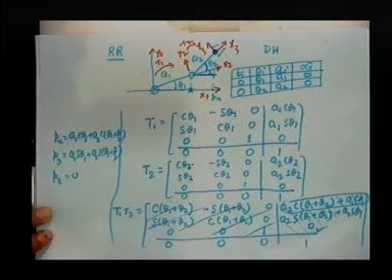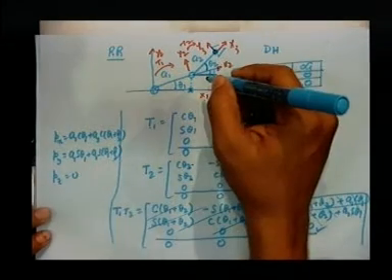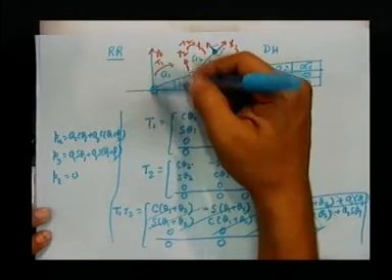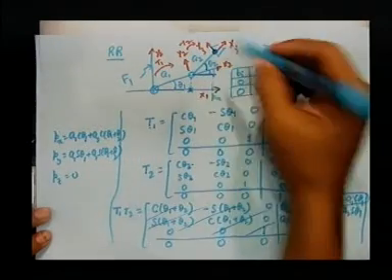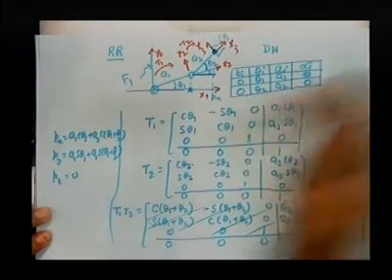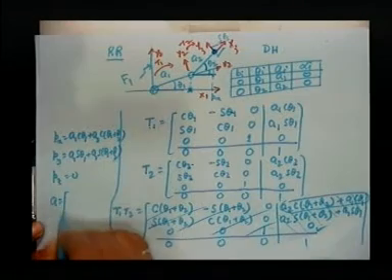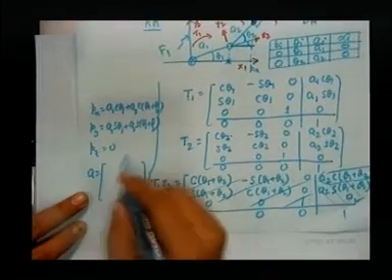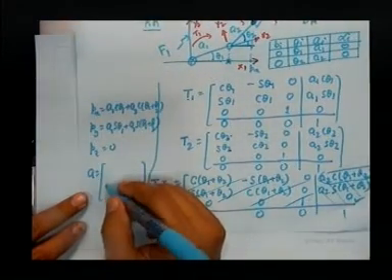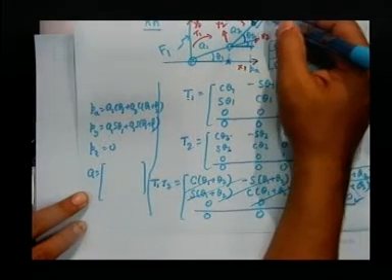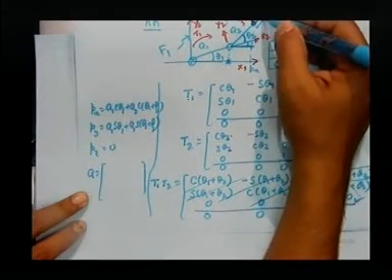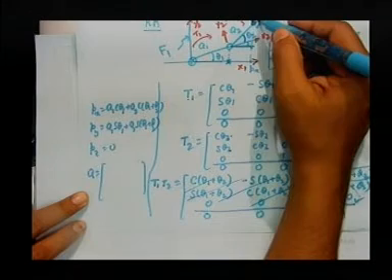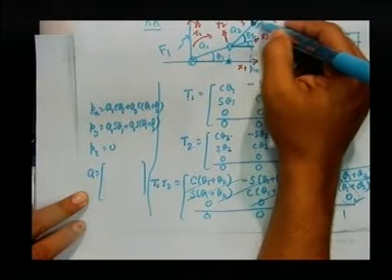What about the orientation matrix now? Now, remember our direction cosine information. I am interested to relate this frame here, which is my frame 1, and frame 3. As per our direction cosine information, the first column of my Q matrix is nothing but the projections of this x3 on x1 and y1. What is the projection of a unit vector x3 on this?